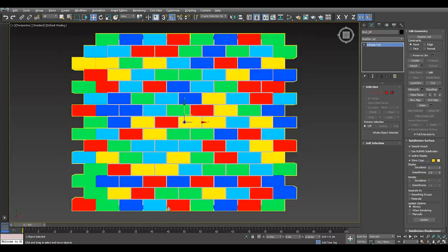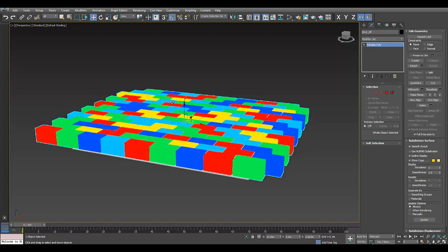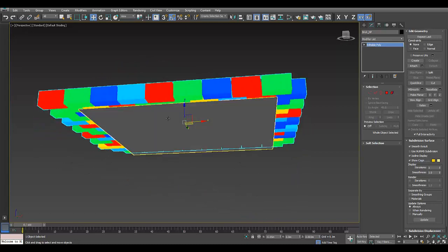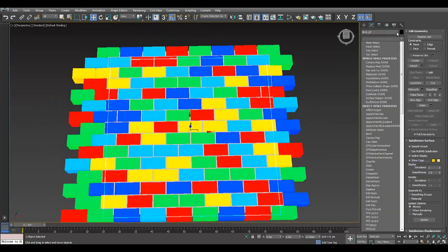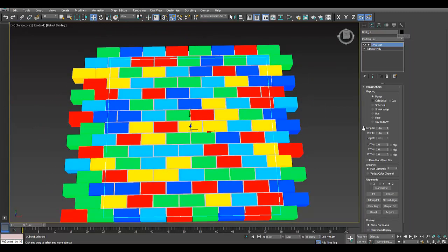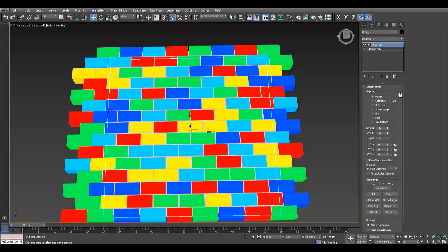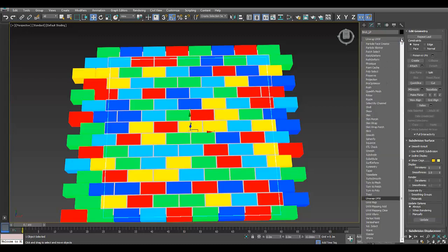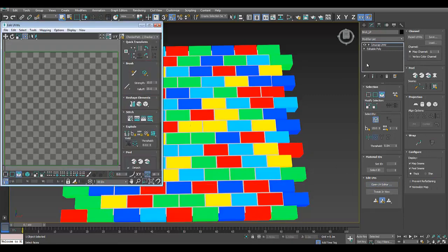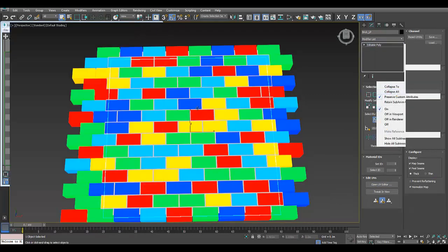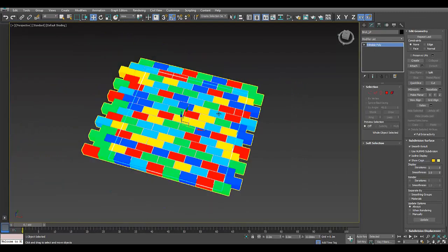So the next thing I want to do is begin setting this up so we can render this colour ID onto this plane. So what I'll do first, with our plane selected, this does have a UV map on it. I'm going to just quickly check to make sure. I want to open this up. Oh, sorry, that's the unwrap. Open UVW. Yes, that's square. That's fine. Right click, collapse all. Close it. So with the plane selected, I'm then going to press 0 on my keyboard.